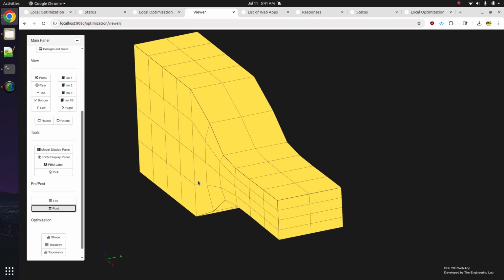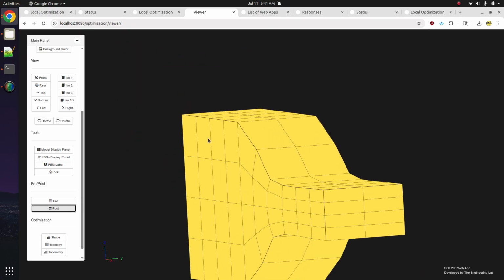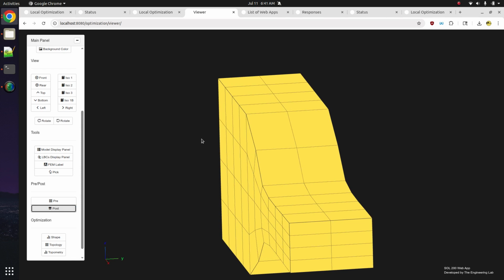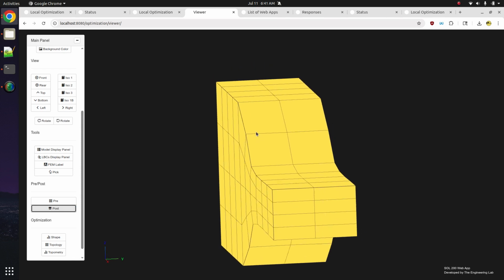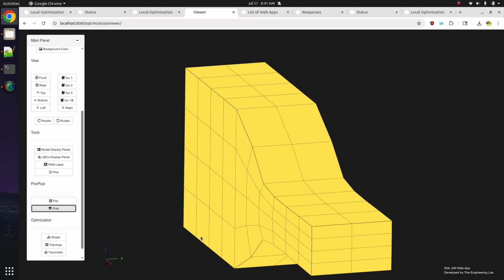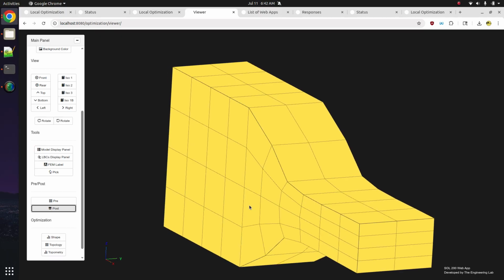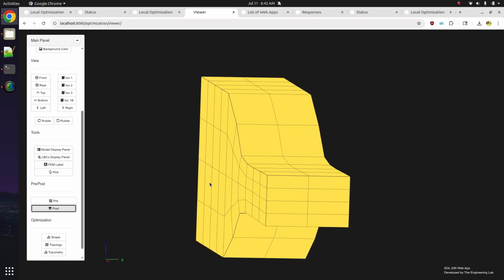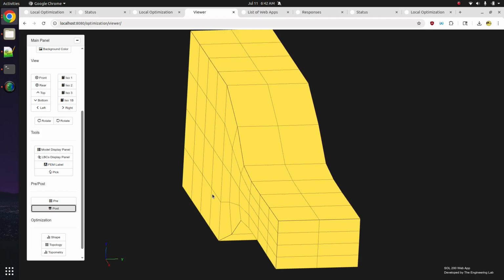Part of the reason that's not possible is because here you can see that the way you reduce the stress in this example is you just keep expanding or increasing the depth of the beam. So you add more and more material here and here near the root, and then that will minimize the stress. That's not really possible, in my opinion, for this cantilever model. If you're dealing with an axially loaded bar or plate elements that are subjected to in-plane loads, that's where you could have a so-called fully stressed design.